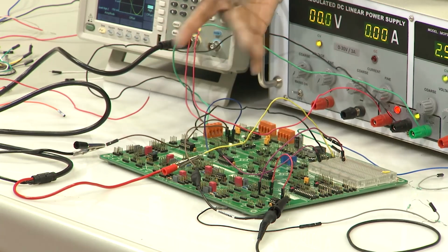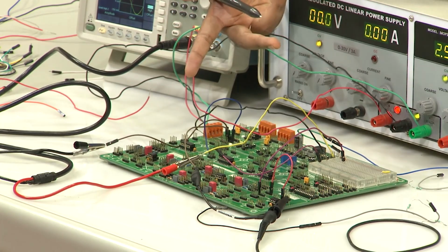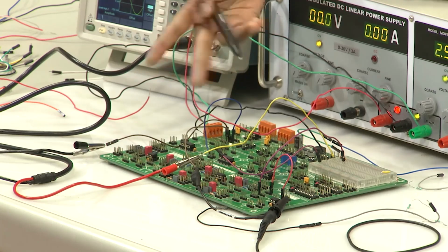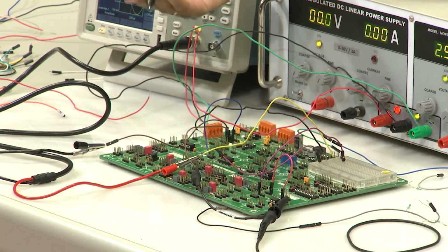If you use the inverting amplifier as the circuit for the voltage follower, what will your gain relationship be? Minus R2 by R1, right, but your R2 is 0. So, your gain will be 0. That is why we use the non-inverting configuration. For the non-inverting configuration, the gain is 1 plus R2 by R1. Here your R2, because you are connecting from the output back to the input, is 0. So, 1 plus R2 by R1 gives you effectively 1 plus 0, so the gain is 1. So, you get a gain of 1, and we are connecting it in a non-inverting configuration. That is the overall idea of how the circuit is designed.